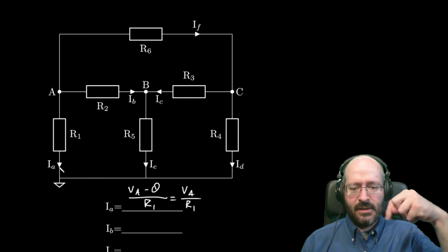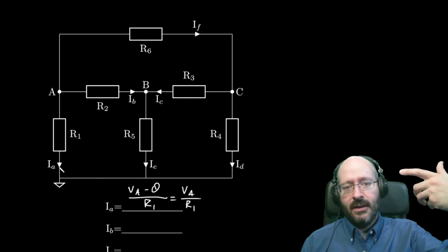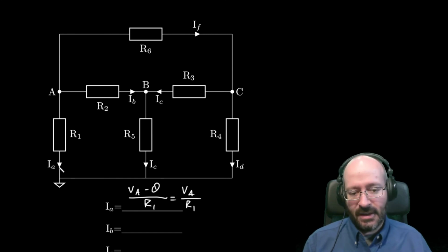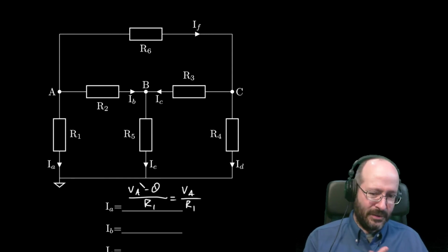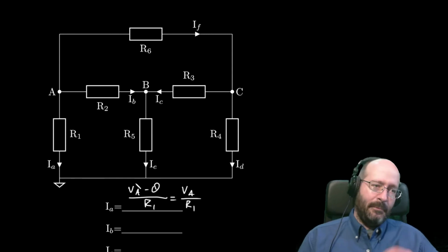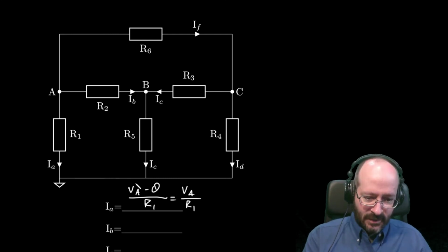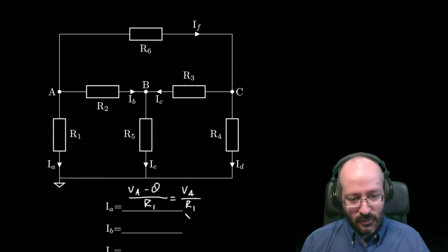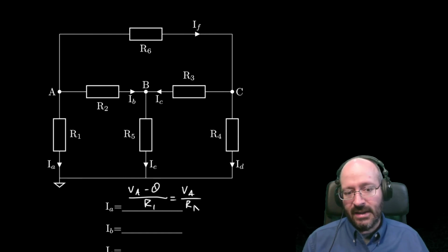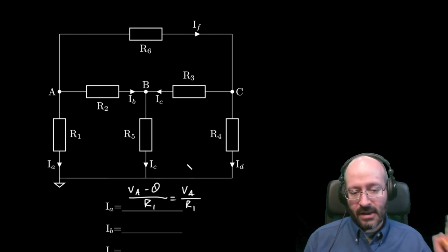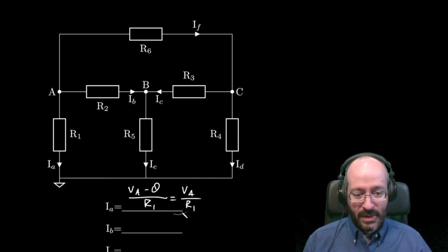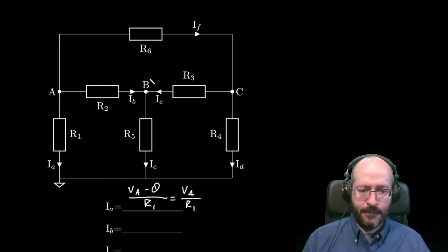It was facing that way, now it's facing that way, and I can indicate that with a negative sign. If we follow the procedure, the voltage at the tail minus the voltage at the tip over the resistance, we can not screw up. We get the negative sign correct in the top one, and we end up without a negative sign down here. So we're good to go.